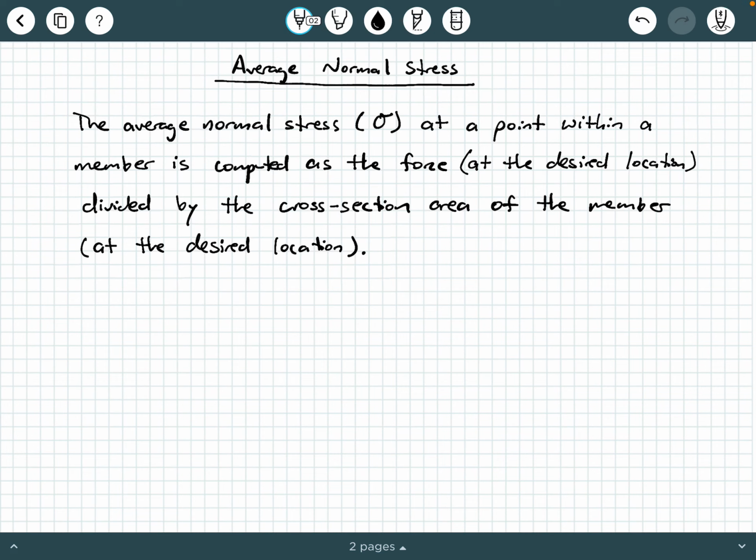Hi everybody, Dr. A here, and in this video we are going to be giving some background information on average normal stress. So what is average normal stress? Well, basically it is computed as the force at a point within a member divided by the cross-section area of that member at the desired point or the point of interest. And we typically use the Greek letter symbol, lowercase sigma, to designate average normal stress.